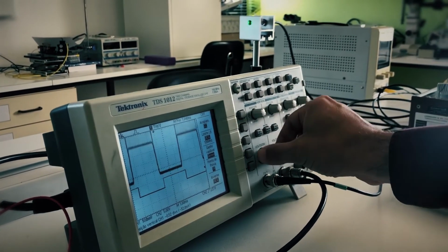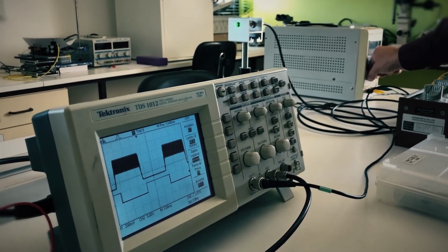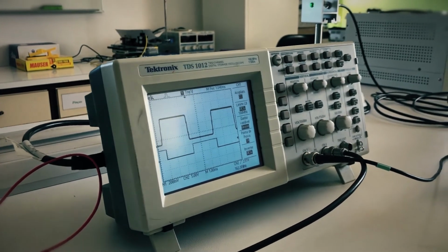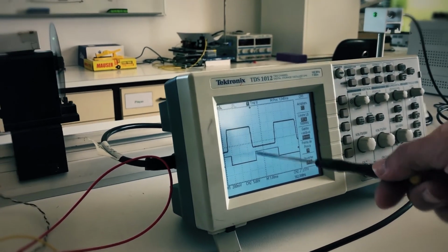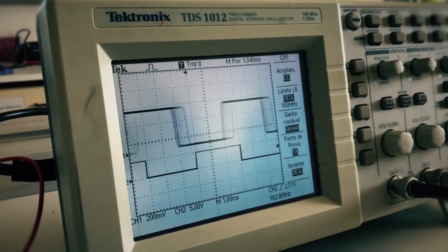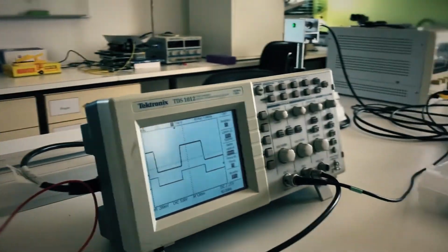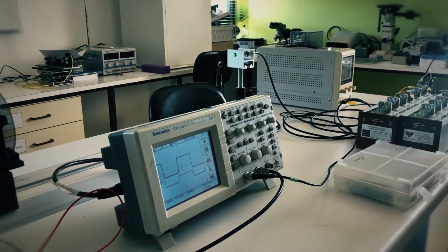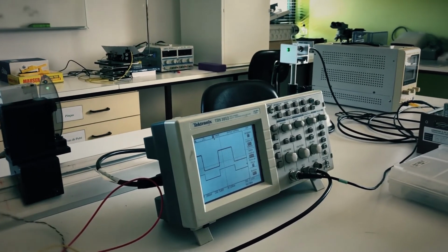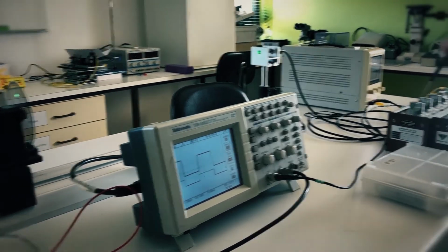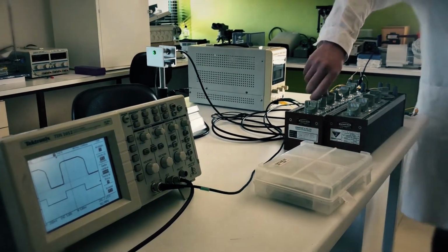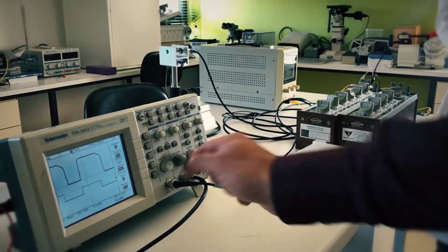Next, a starting value of 300 ohms was set on the resistance box. Observing the response of the photodiode in the oscilloscope, we can see that it is pretty much in conformity to what would be ideally expected. As we increase the resistance value, we notice an elongation in the fall part of the curve, that is, the fall time increases while the rise time stays unchanged. This means that the photodiode continues to output current a bit after the light stimulus is removed.